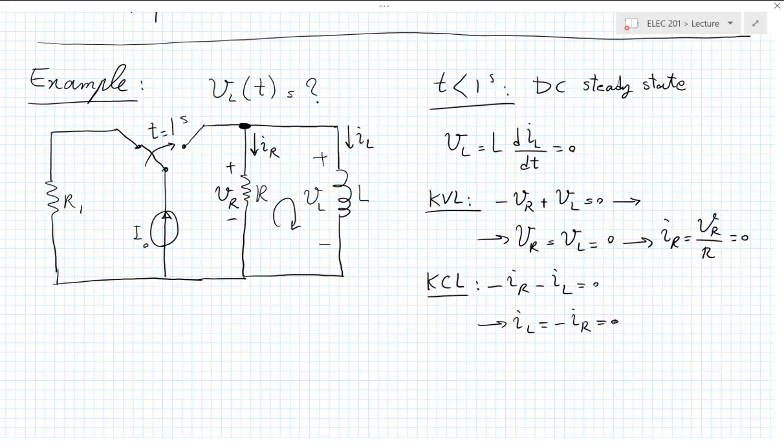There is a reason I put that resistor there, because if I had this current source with I naught not connected anywhere, where would its current go? It wouldn't be happy, right? So that's why I put that there, so that it can take that. And the voltage across R1 would be I naught R1, and that voltage also appears across the current source.